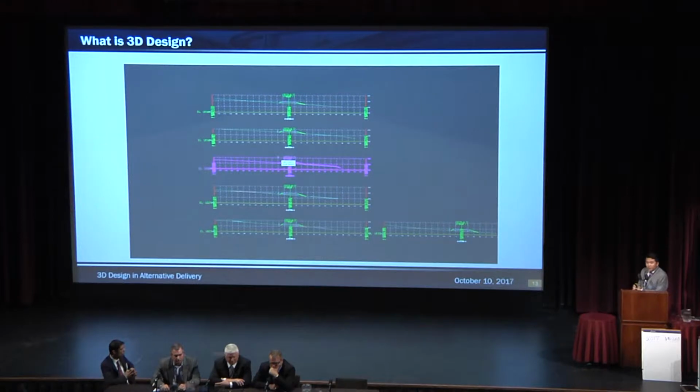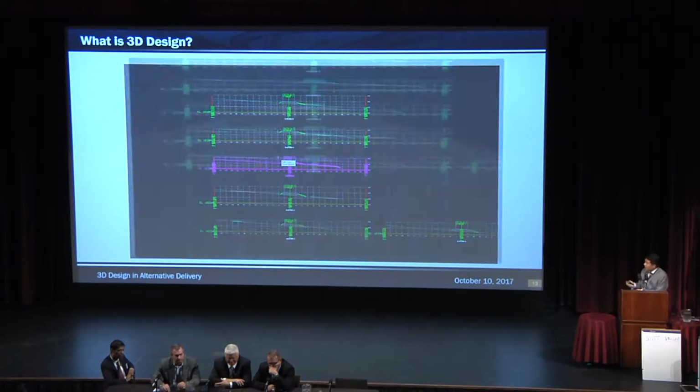All so we can get down to our cross-sections. Now, for a typical design, we'll run cross-sections every 100 feet, or every 50 feet, every 25 feet. But we don't get to see every detail unless we purposely make every detail. If we want to cut a section in between section 5 and 15, we have to purposely make a section there, or cut a section, just so we can get these cross-sections.